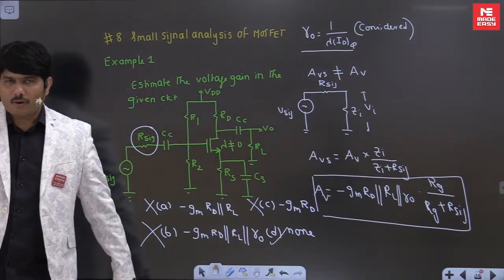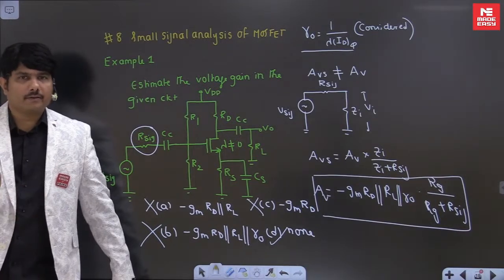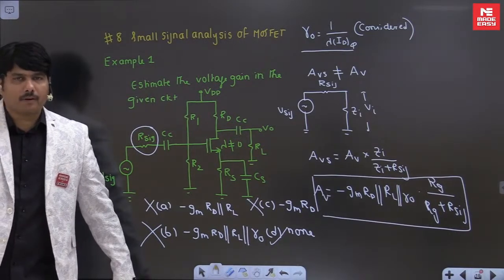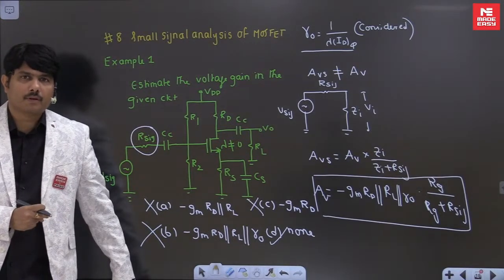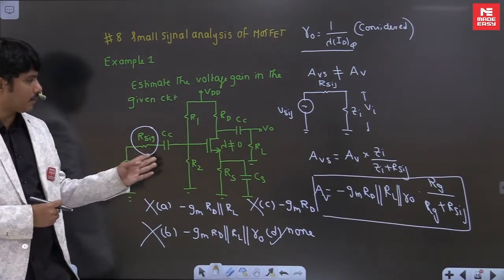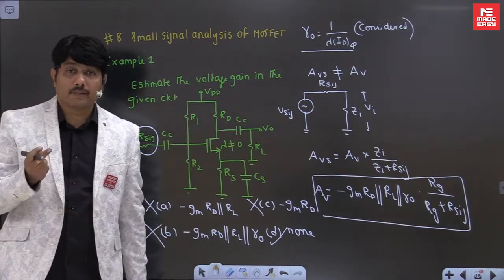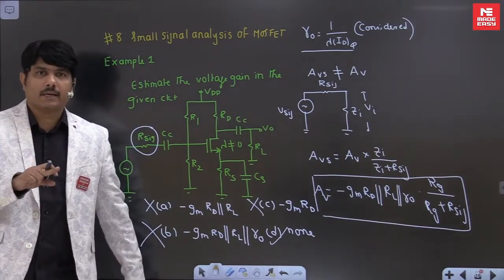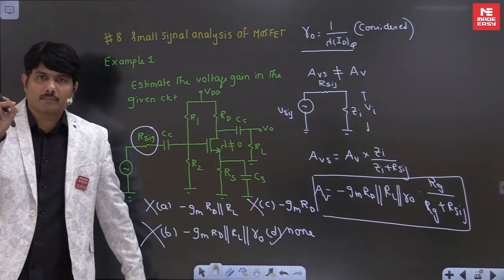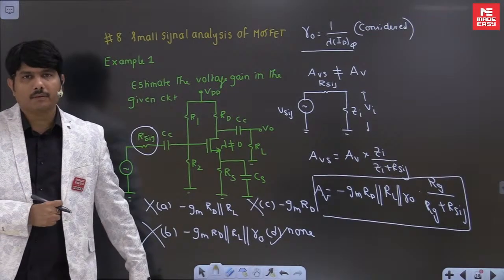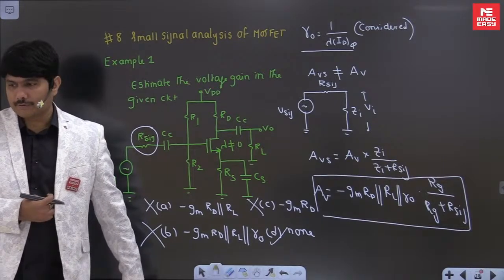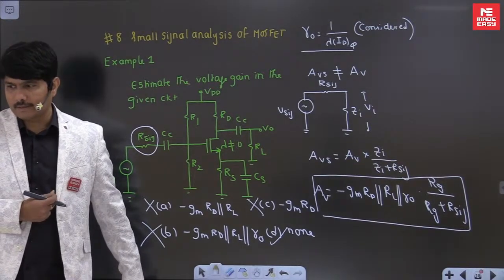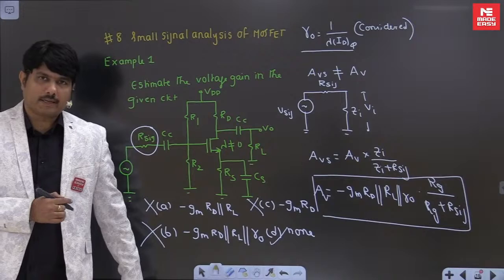So a small concept, logic you have missed. That type of creativity or that type of concentration you have to build up more. Okay. If they give it happily without R signal, this is a simple question. If they give R signal, you have to understand the gain of the transistor MOSFET will not be the same as the gain of your circuit. Okay. Now everybody understood this mistake, please don't do it in the exams.